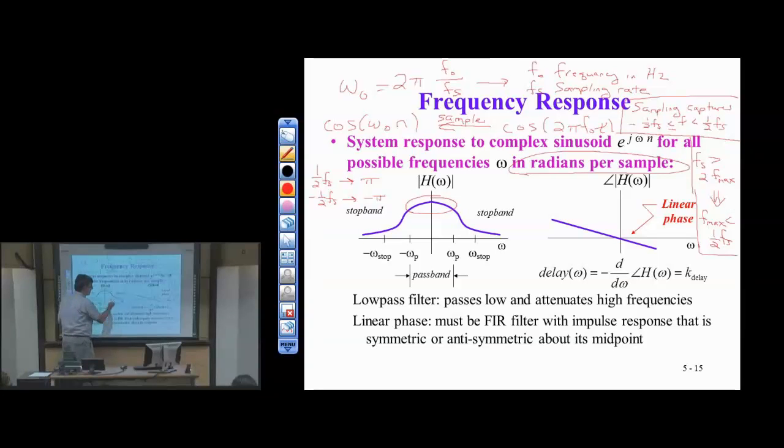At some point, just from applying a threshold, we'll find out where the stop band is. Okay, so there's our stop band. Again, this is somewhat arbitrary. I have to pick a threshold. Sometimes I know it from the design specification that I might be given. Eyeballing this, at some point I have a stop band, which means I'm reducing dramatically those frequency components as they pass through the filter. Remember, this is the filter's frequency response. I then have this